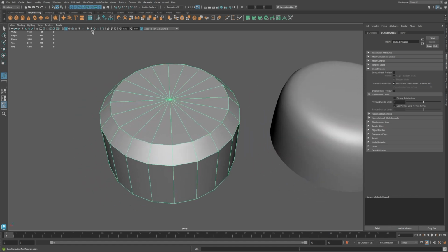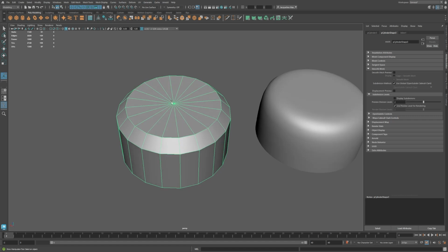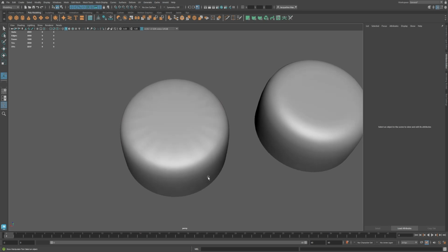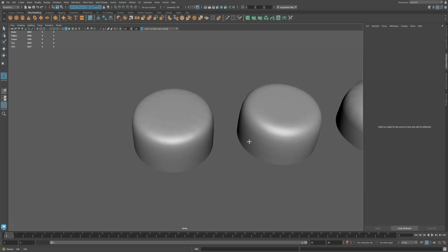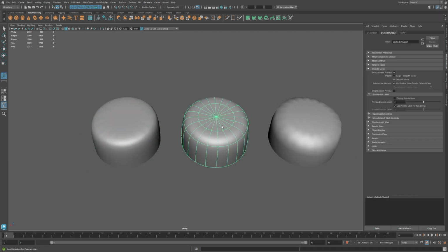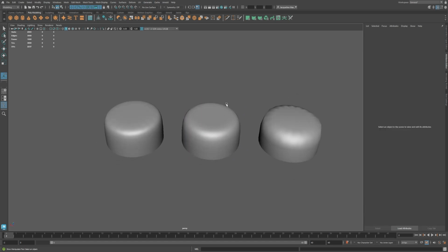So then let's look at this other scenario. In this one, our triangles are inside an additional ring, but this is a beveled edge. So it's not serving as an additional edge on the same surface, but it's starting to change in volume. When we smooth this, you'll see that it's still getting that starburst effect, where we can see these rays coming out and a ballooning effect around it. So the takeaway here is that we need to make sure things are contained with holding edges if we're ever going to be using triangles on a surface like this.